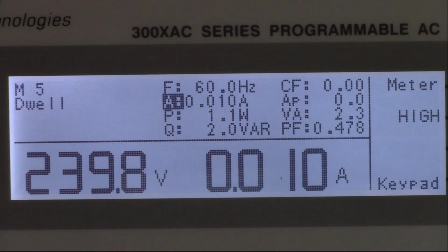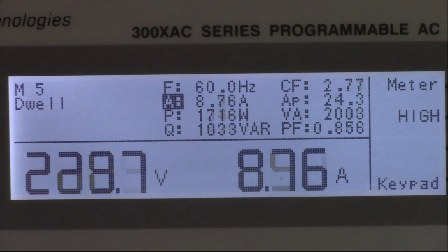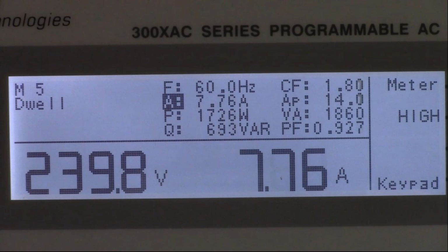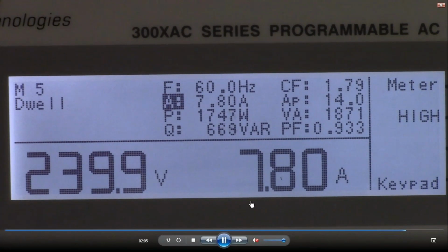You can see here that we're applying 240 volts, and then when the motor turns on, it draws 19 amps. So I saw 19 amps come up there for a few seconds. The voltage was dipping. And then what we saw additionally is that now it's at a steady state. So this power supply could meet the requirements for steady state, but was not able to meet the inrush requirement. But having OC fallback allowed it to power up this vacuum motor successfully.